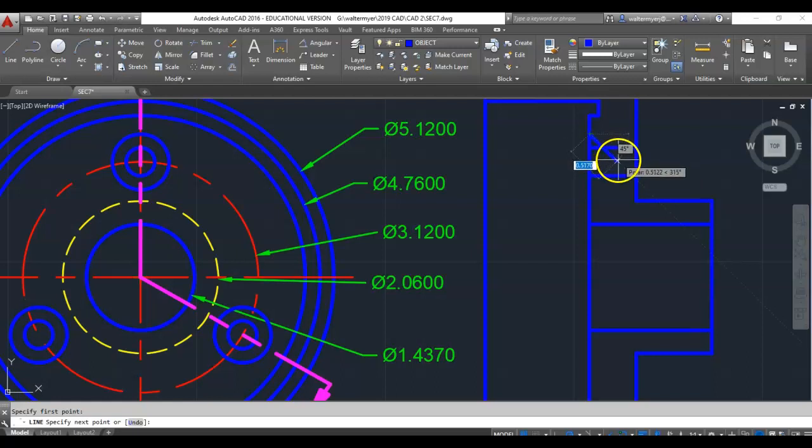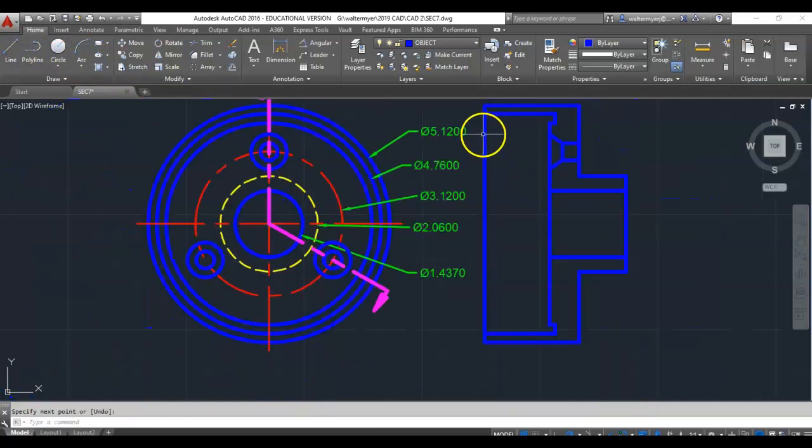Basically that's angled face from angled face. So I'm going to hit tab 35. Bring the other side. Tab 35. I'm going to trim. There, there, and there. That gives me a new edge. So I'd have a line.